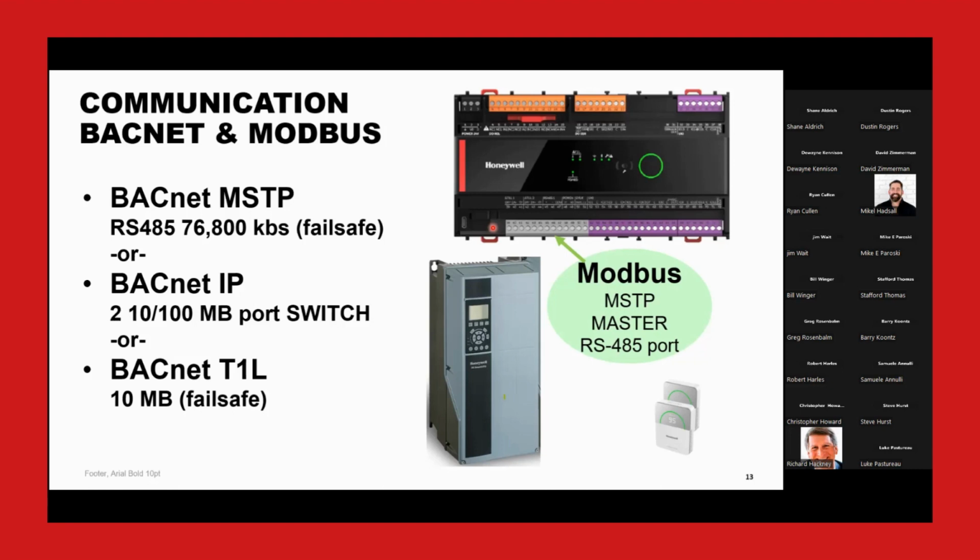If I have a VFD controlling it, and I put this on the air handling unit, instead of using an analog output to drive the VFD and then maybe a digital output to turn it on, a digital input for alarm, instead of using up my precious I/O to drive my VFD, which is 2 feet away in a cabinet, I can run a 485 bus to it, talk Modbus over MSTP to the VFD, and pretty much everybody's VFD will do that. That's pretty standard in the industry.